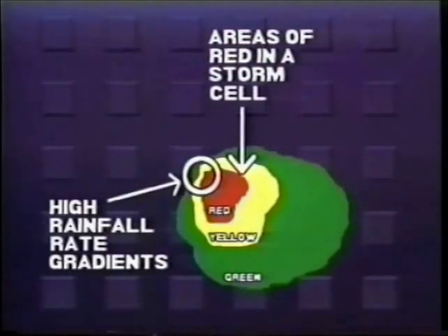Weather cells, which are very active, often called thunderstorms, have high levels of turbulence and excessive amounts of precipitation contained within them. Flight crews can learn to recognize these thunderstorms and assess their hazard potential by looking for the following characteristics. A rainfall rate anywhere within a cell displayed as a red color. The amount of danger a storm represents to an aircraft is strongly related to the rainfall rate within the storm. A storm which is displaying red rainfall can always be considered a threat to the aircraft and should be avoided.